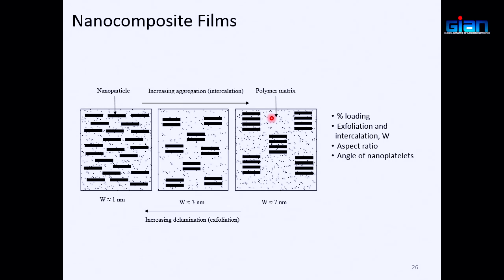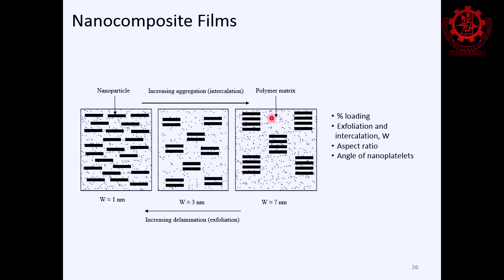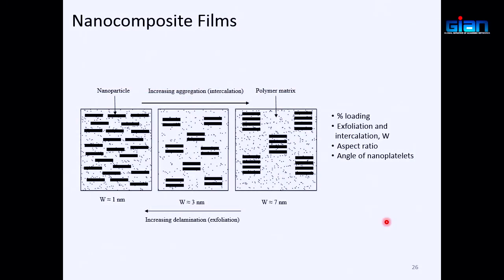Okay, this is the general information about permeation of gases through packaging films, some fundamental concepts, and then how do we measure that permeation of the gases as well as vapor. We have hundreds of different polymers, but for food applications we have some 8 to 10 polymers which are used. In that we do have a range of permeability or the oxygen barrier property or water vapor barrier properties.